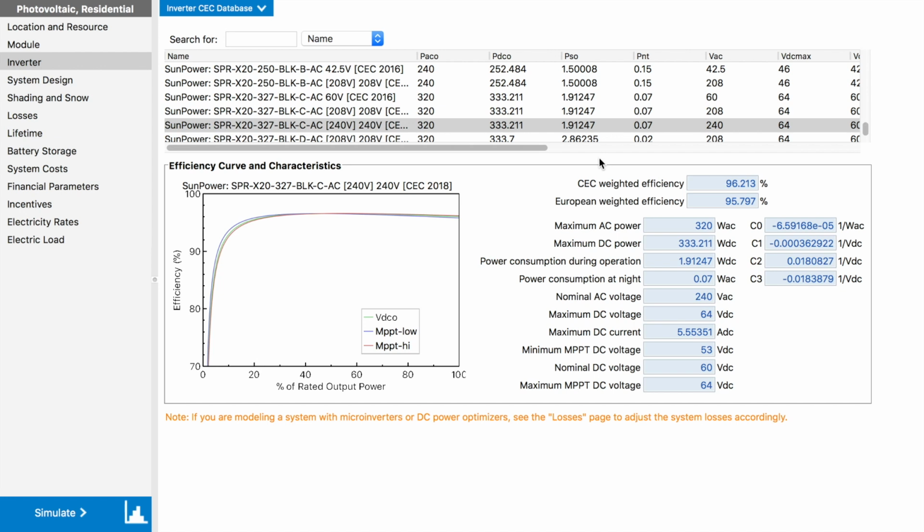Microinverters allow the entire array system to stay operational even if one panel is shaded and not able to produce power. Without individual microinverters, the entire array system would shut down if one panel was shaded. Think of this as an open series circuit, and microinverters wire the array in a parallel circuit format. Since the inverter already is included with the panel, we're going to select the same microinverter model, making sure to choose the same voltage as the panel. This voltage refers to the voltage output and efficiency of the panel. If we choose a panel without the built-in microinverter, you would just have to choose an efficient inverter that works with the module you choose.